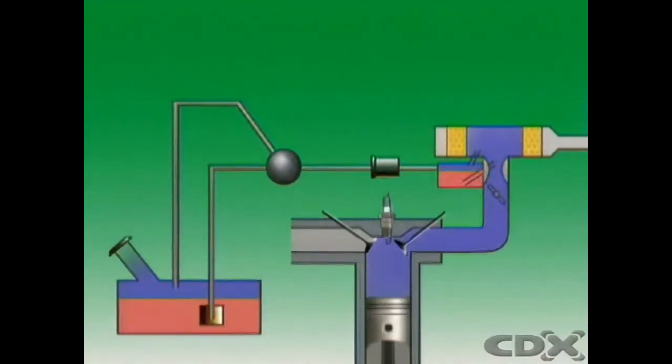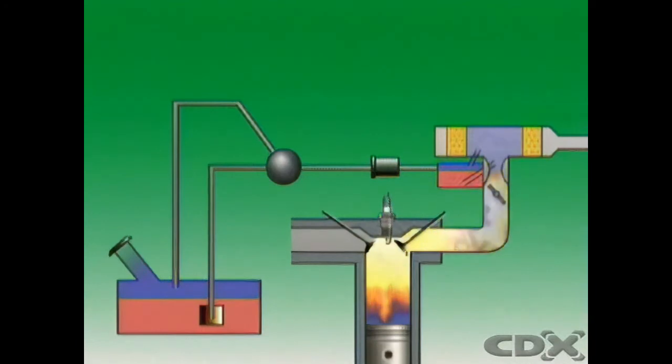The filter also has a silencing effect, muffling noise produced by the air entering the engine. It can act as a flame trap, so if a gasoline engine backfires, the air cleaner can contain the flame within the intake manifold or carburetor.